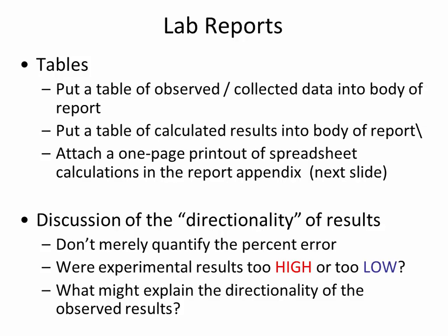And so you need to plausibly explain the reason for the error. So what's implausible? I noticed one set of calculations where the theoretical metacentric height, calculated using the theoretical equations, was maybe 0.07 roughly.